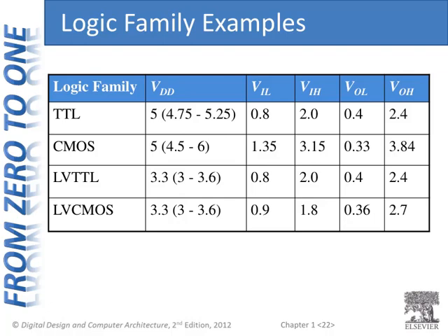Okay, so let's look at some different logic families. If you're actually buying chips or going to the lab and working with chips, being aware of what logic family is operating is useful to be able to tell whether they will work together. So for example, let's do some examples here. We have these specifications: the nominal VDD, the input characteristics, input low and high, for the gate, and the output characteristics, output low and high for the gate.